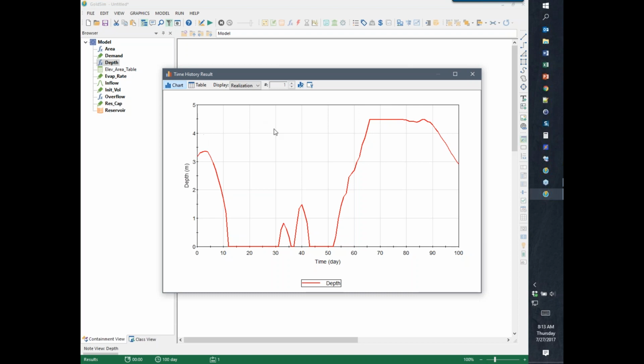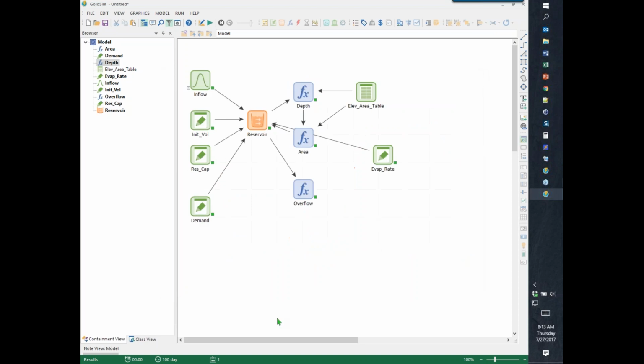Up here at 5, this is where the capacity limitation is of the 1,000 cubic meters or megaliters. And so let's say that what we want to do is put in a pump station that delivers water into the pond and maintains a level of, let's say, 3 meters. Actually, let's just say 2 meters, so we're about halfway in between. So we'll build a pump that will deliver water into the pond to maintain about 2 meters in the pond.